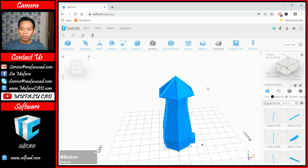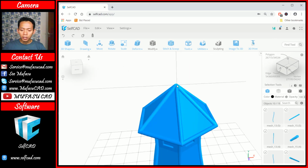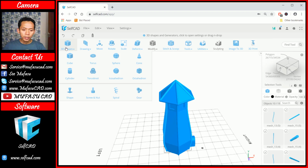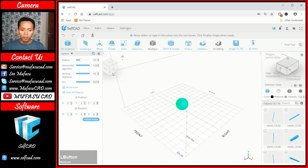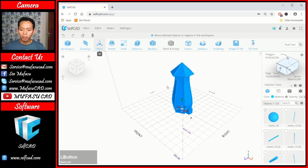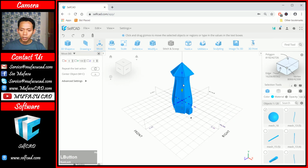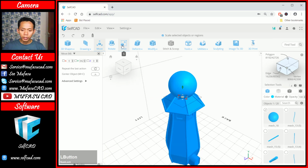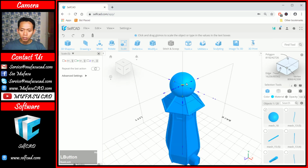Okay, we create a sphere at this top object. You can click 3D shape, click a sphere. Okay, you can click apply. You can use the move command to move this sphere. Okay, you can click at this point and move to the top. We can use the scale command to scale these models. Okay, make it small, and then you can close.